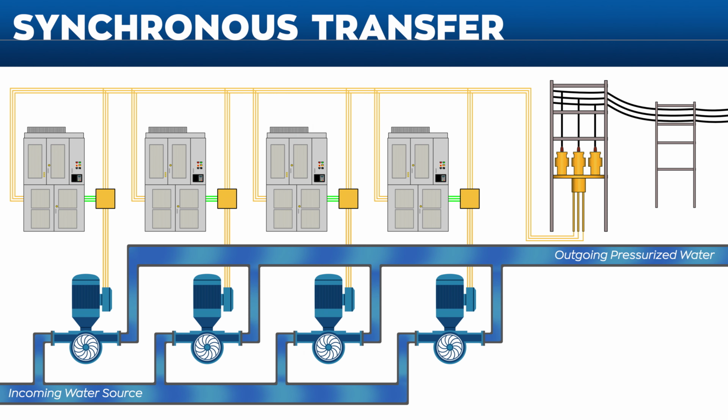For example, a water utility may have periods of varying demand throughout the day. During periods of low demand, 1 pump may be required at partial load. During periods of high demand, 4 pumps may be required, each running at full load. Now, this is an effective solution. However, it may not be cost-effective to have a drive on each pump if they're only needed for peak demand.